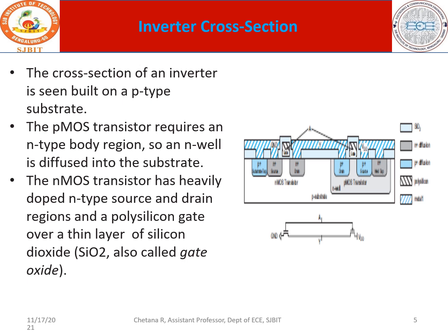You notice, this is your substrate. On your substrate you have a well structure. Here it is an N-well structure. On the N-well structure you have P diffusions, and this is your N substrate. This is your P substrate, and you have N-type diffusions. Likewise you have the polysilicon structure over here, which is nothing but our gate terminals.